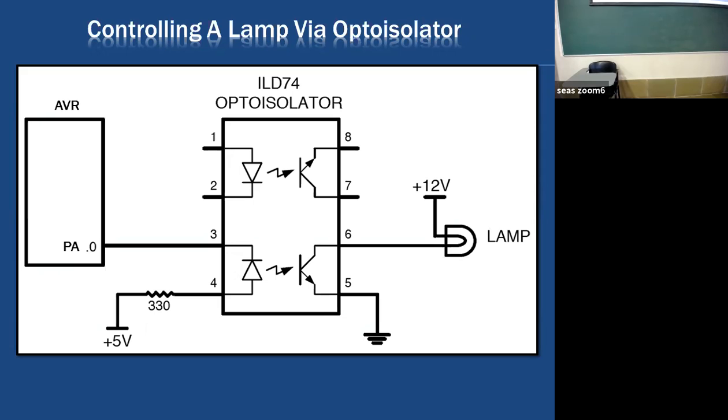So optics is involved, so we call it an opto isolator. And isolation is good because suppose there is some source circuit here. Now there is no electrical connection from this side to this side. Only light is there. So any short circuit here will not damage anything on this side. They are isolated.